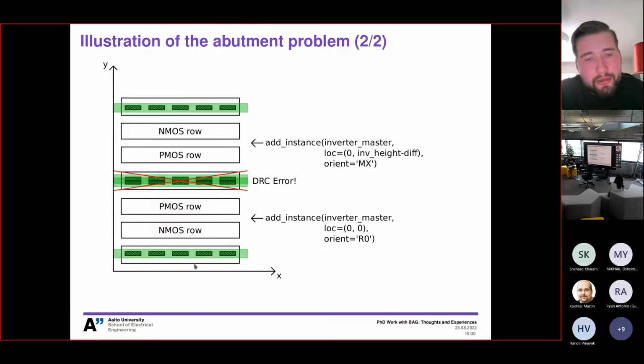So you have to know what in your technology specifies this distance between the y0 and the bottom coordinate of your substrate. And then once you know that number and add that to half of your substrate height, you can always round that up to the track pitch. So basically changing your substrate width to center the track. Then if you do that, you will always guarantee that your substrates are symmetric with respect to the template, and you can overlap the substrates and save some area there.